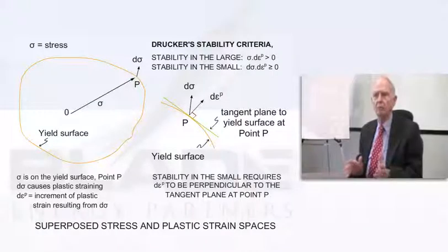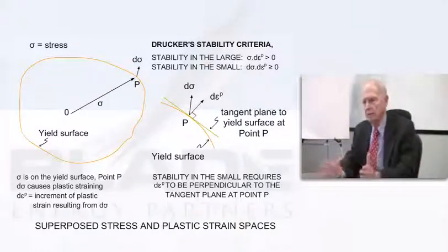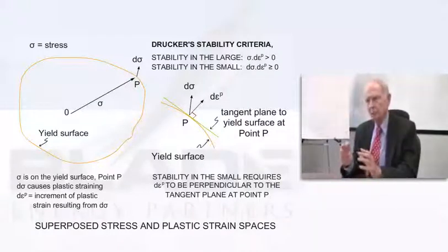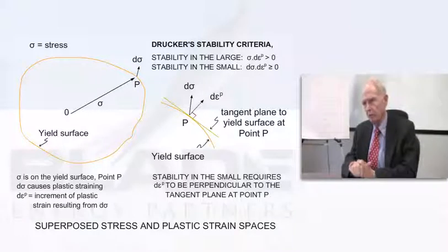And the reason for this is that when I have a material, and maybe because it's a polycrystalline material and it's got slightly different orientation of all the grains, I think you're pretty close to having a uniform strain in the body rather than a uniform stress, because of the slip planes acting in the grains.